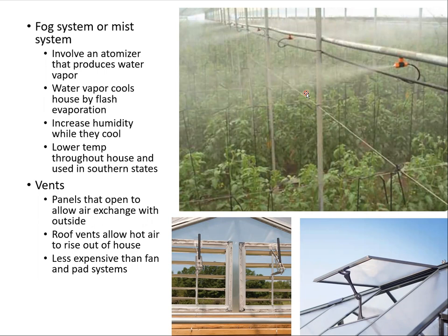They use these the same way in greenhouses to be able to cool the air, because you kick up the humidity, you get those water particles in, and you need an atomizer that produces water vapor. The water vapor cools the house by flash evaporation, increasing humidity while they cool. The lower temperature ends up throughout the greenhouse and is used typically in southern states.